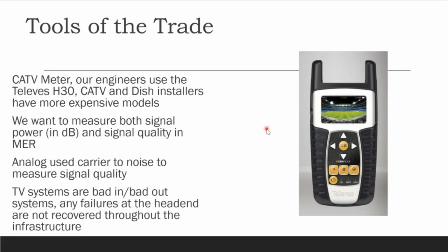A high modulation error rate means your TV isn't going to be able to pull enough of the good stuff out of the picture, and you're going to end up with pixelization or color bars or potentially green screen and blocks, because we can't process the data that's there due to the amount of errors in the data. So you just end up with null data, which doesn't present well on a TV screen.